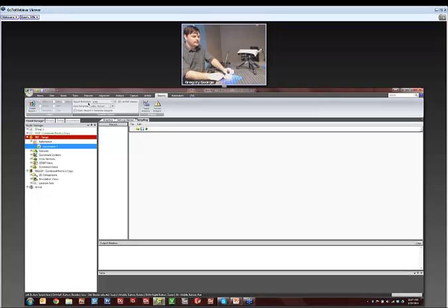You've got to remember too that you don't have to have the targets on the part. You could actually set the keyboard on a table that has targets all around it, and as you scan, it adds the targets to the current overall target coordinate system in a way. So you could set that keyboard-sized object on a table with the targets already on it and work your way around it. Really, that size is only 2 volumes big, so you would still be able to get very good accuracy, I think, between all the scans.